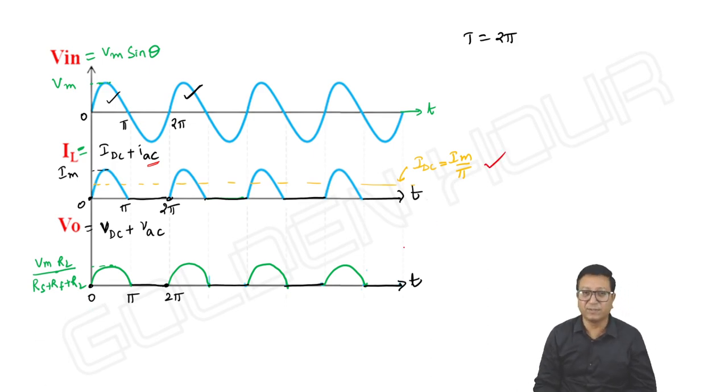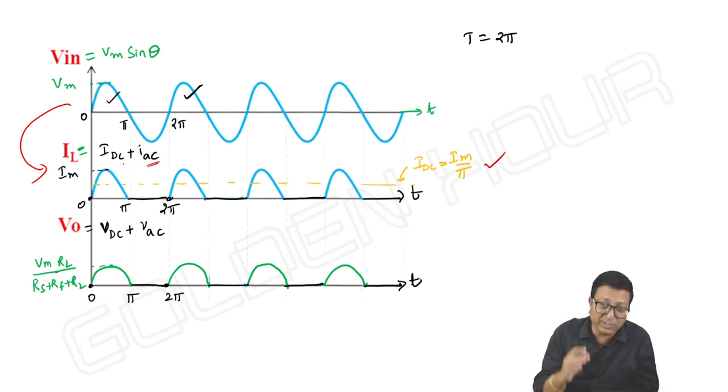This is the only DC you are getting. Okay, what you are doing first is converting this AC into pulsating DC, or bipolar signal into unipolar signal, and that unipolar signal is not completely a DC component, it is a combination of DC and AC. We are expecting only DC, but we are getting some AC which is known as unwanted AC.